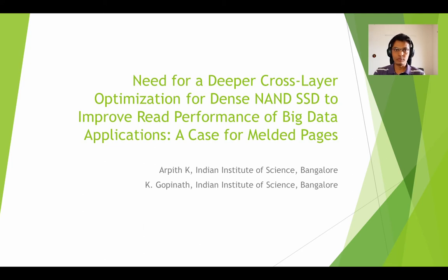In this paper, we propose a solution which combines various page types in a word line into a single logical page called a melded page. It uses the knowledge of I/O patterns of the workload to improve the read performance of NAND-based solid-state drives by mitigating the overheads involved in the read operation.